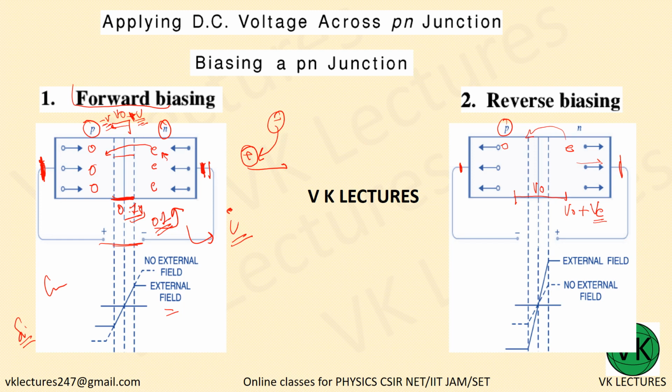Now again, coming back to reverse bias, once you apply a very large reverse bias, what will happen? Same process will happen. Electrons, when given more potential, will start hitting the nearby electrons which are covalently bonded. Again, there is a rise in temperature, holes will be formed, electrons will start moving out. Again there will be a rising current.